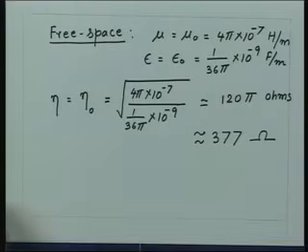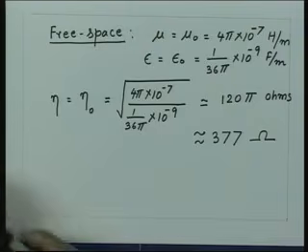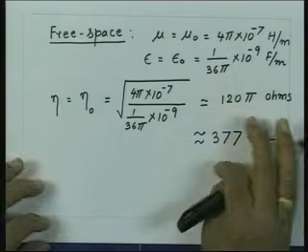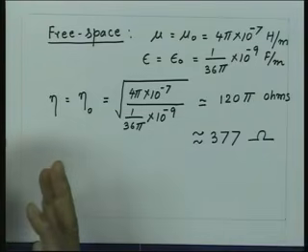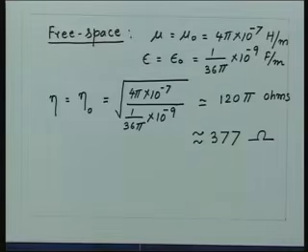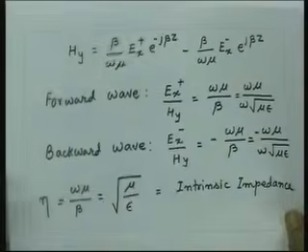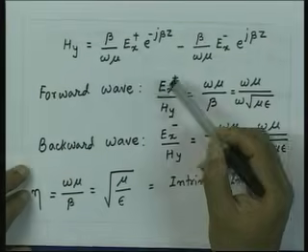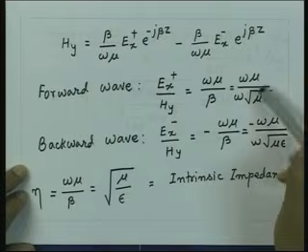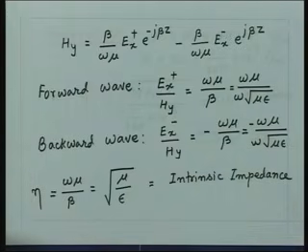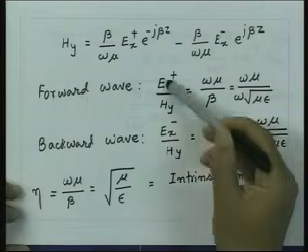So, later on when we go to the discussion on antennas or other propagation, this concept will be very handy: the space will be treated like an impedance of 377 ohms to which the power is to be delivered. So, from here we see that once you get this parameter, which is the intrinsic impedance of the medium, the ratio of the electric and magnetic field is equal to the intrinsic impedance of the medium, which is eta, and that is true for both the cases.